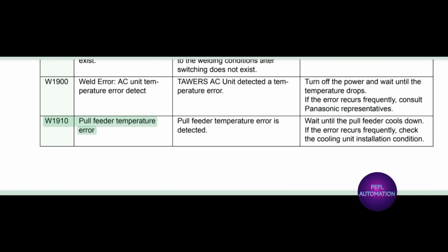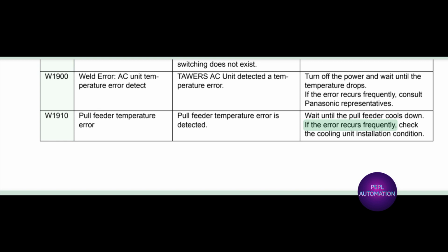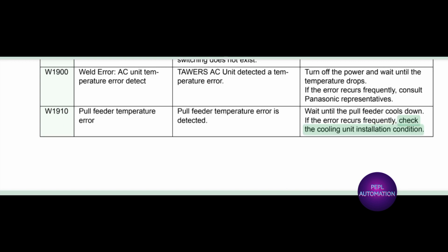W1910 pull feeder temperature error. Pull feeder temperature error is detected. Wait until the pull feeder cools down. If the error occurs frequently, check the cooling unit installation condition.